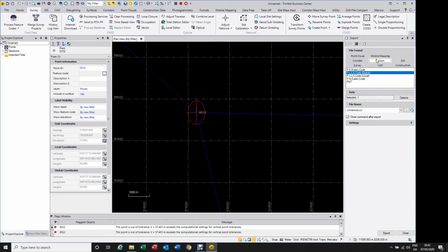If you can export it like east-north elevation and code, point number, east-north elevation, code, then it will export these grid coordinates, which is alright, because next step we can start with a job with ITM, or you can export it with a global point latitude, longitude, ellipsoid height as well.